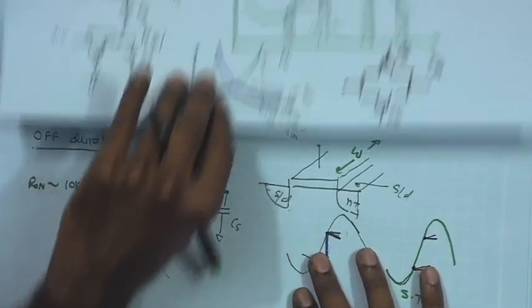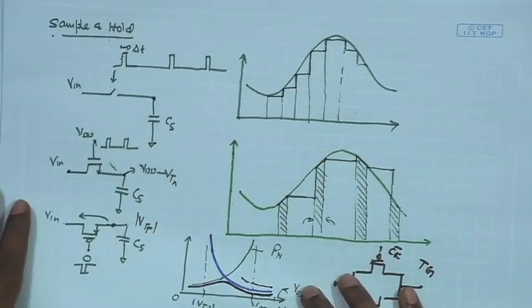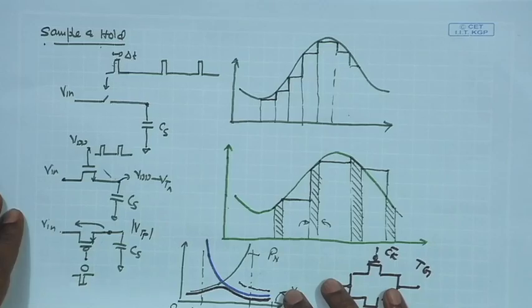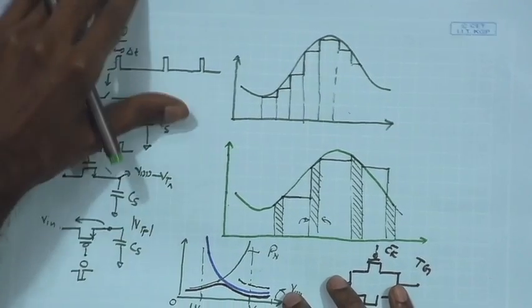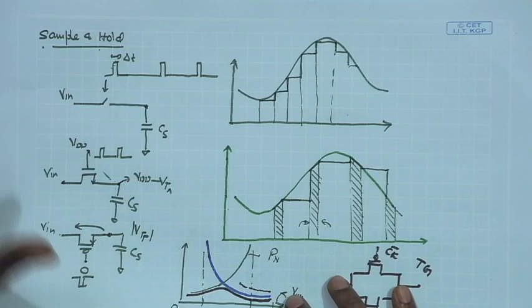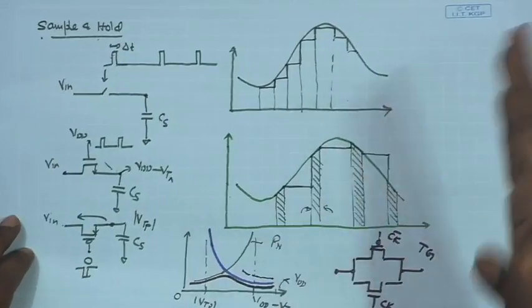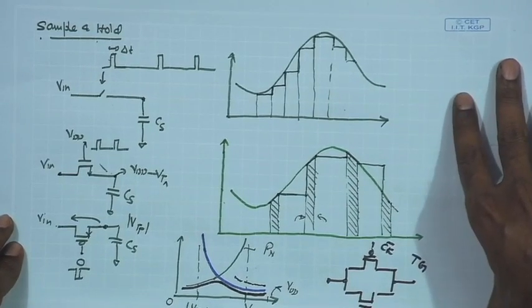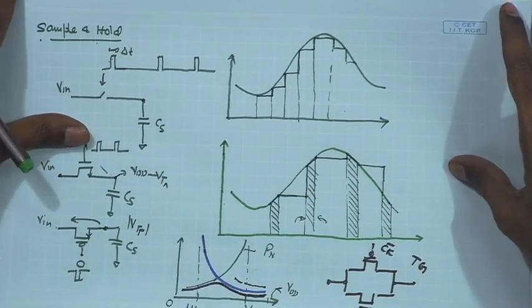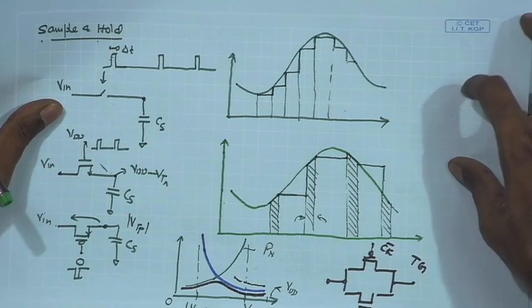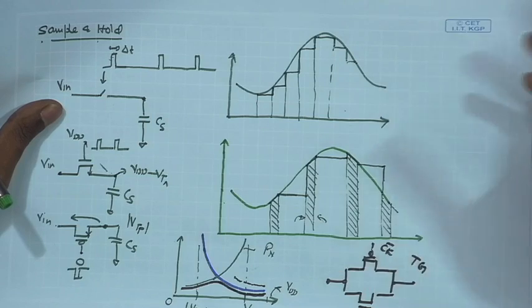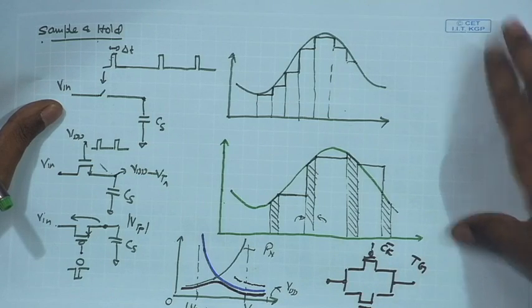So, in our case, the sampling period will be determined by the signal frequency content, and if you recall our signal frequency content for the neural potential that we have discussed, this maximum frequency content may be a few hundreds of hertz, at the max say kilohertz, and as a result we would expect that the sampling frequency is say a few kilohertz at max. So, suppose the maximum signal content is say 1 kilohertz, and corresponding to that the sampling frequency that you are getting is 2 kilohertz.